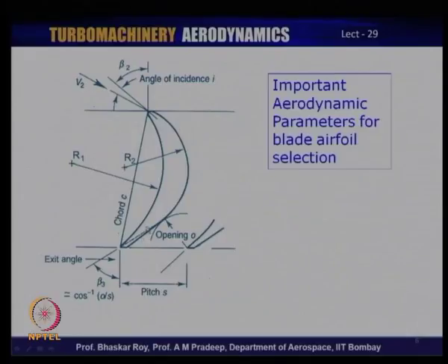And these blades in the classical design, the circular arc is followed by normally a straight line on both the surfaces, and then a little rounding at the trailing edge and then a rounded leading edge. In many of the modern designs, the rounding at the leading edge is very prominent or very large, essentially to cater to the cooling technology to be embedded inside it.